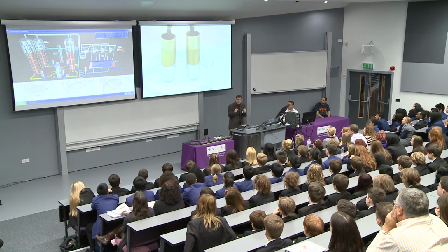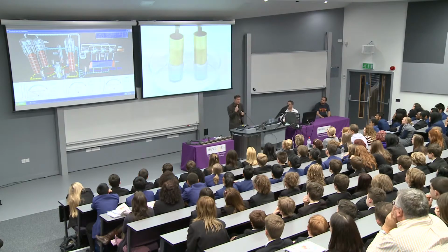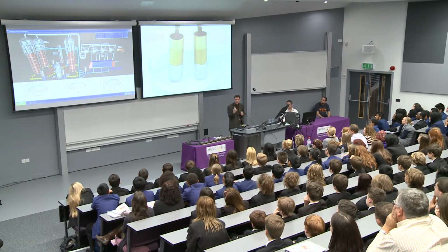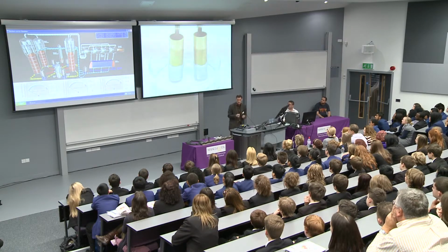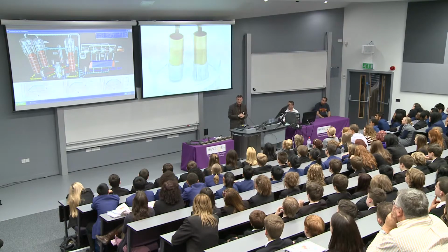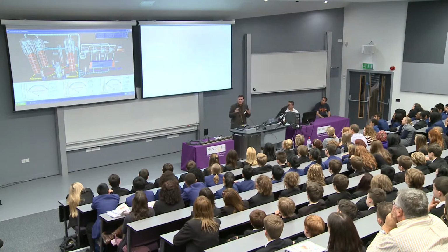So these 2 brass tubes, the one on the right has got an internal stress. It's called a hoop stress, and it runs around the circumference of that cylinder. This is put into mercury chloride. And if you watch the one on the right, you can start to see cracks forming and growing up the length of the cylinder. And it's the stress there that's driving those cracks. The one on the left was stress relieved. So stress and strain has an important influence on the way components behave. And we'll come back to that a little bit later.